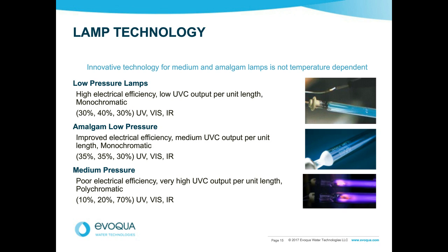Yeah, okay. Well, look, low pressure lamps are built to be rich in 185 nanometer light. They also produce lots of 254. So to answer the question directly, no, you don't need a second UV system. If you've got a 185 nanometer system, then it will also produce plenty of germicidal UV. So both types come off one lamp. You might need different UV systems across different parts of the process. Using UV to remove TOC involves ion exchanges. It can involve carbon, so there could be other points to introduce bugs into that kind of loop. But to answer the question directly, no. If it's a 185 lamp, it also makes 254, so that will also be germicidal.